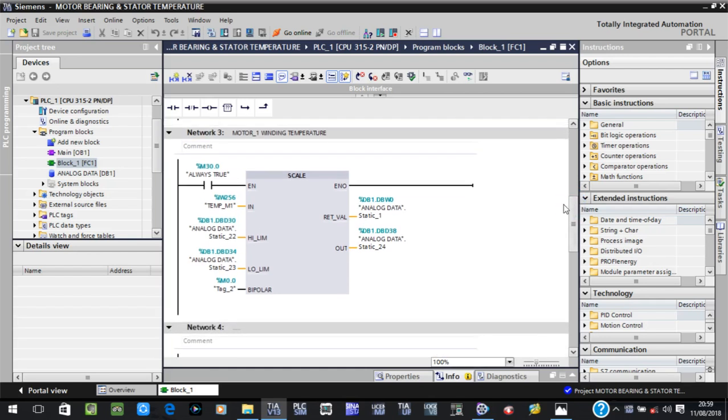The reason we have this scaling block is to convert our standard engineering value 27648 to a form that will present our temperature, our pressure, our water level, because in some instances we need bars, we need degrees, we need liters, we need flow rate, cubic meters per second, per minute, whichever case may be.